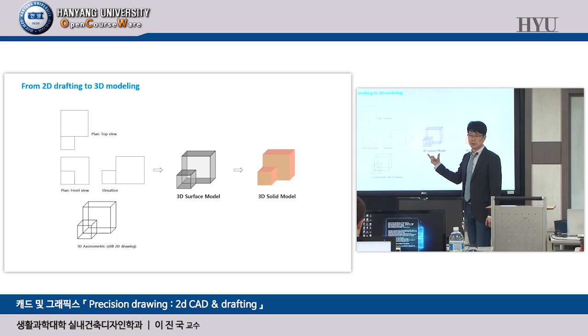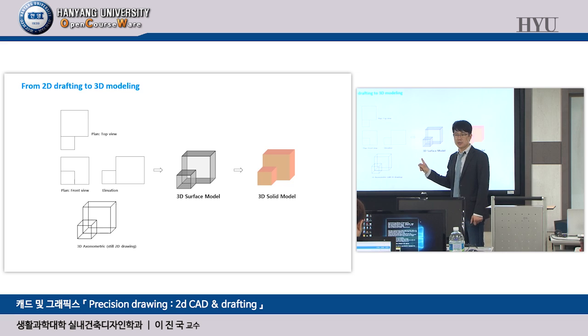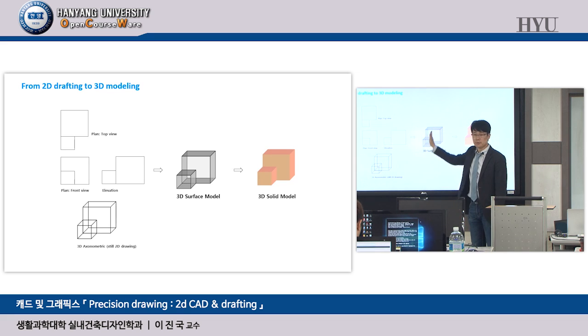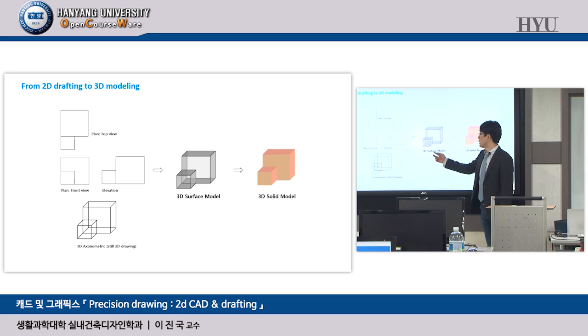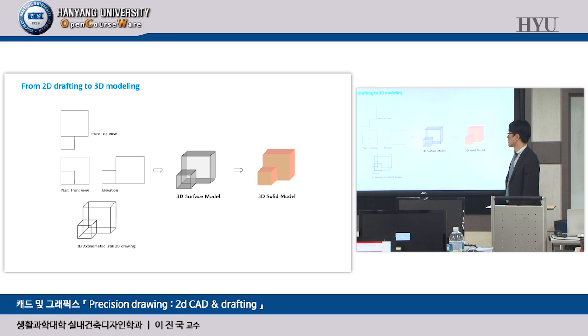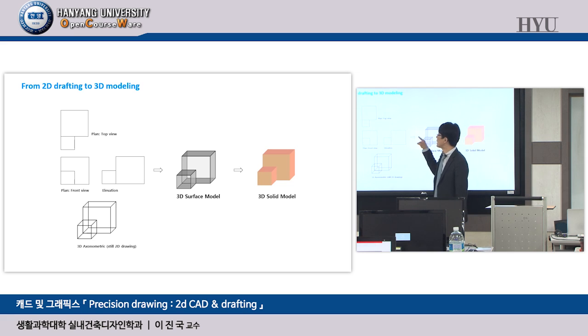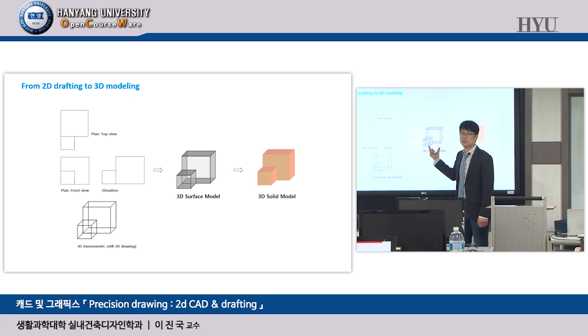If you have a 3D model, you can place your camera with appropriate views, and then you can get front view, top view, right view, left view, even section view. Okay, you can place a section plane, and then you can get specific section views. Whatever it is, you can get this kind of visualization. What I mean is you can extract those standardized views from a 3D model.